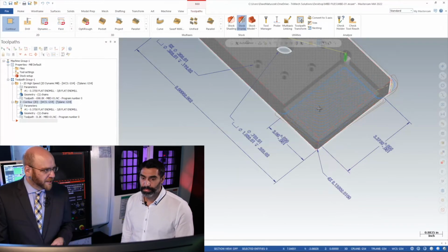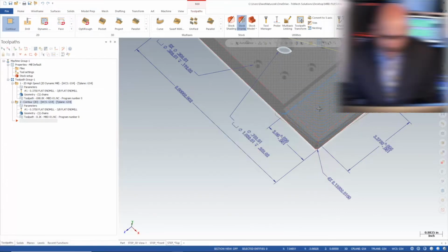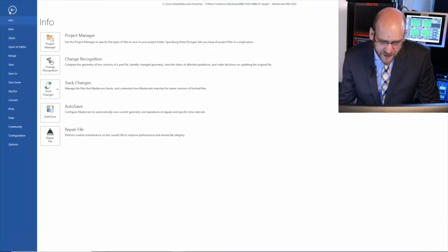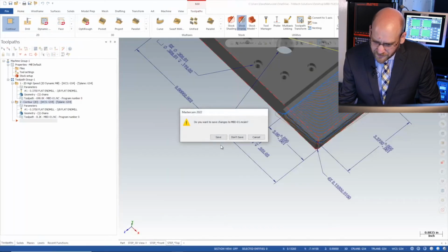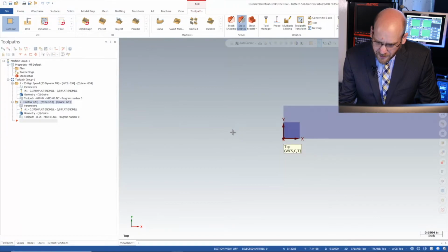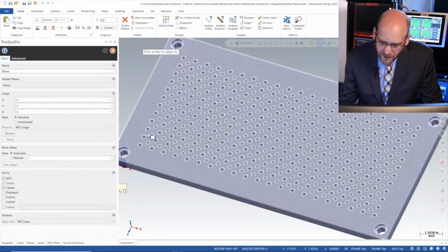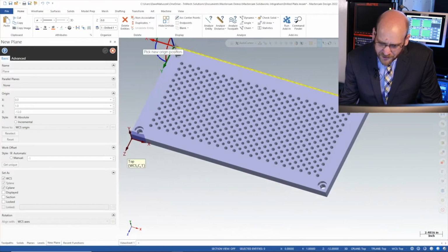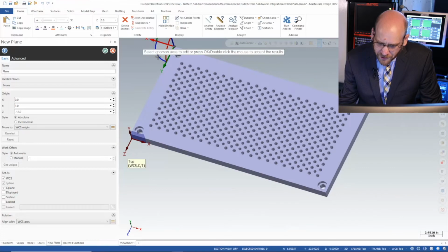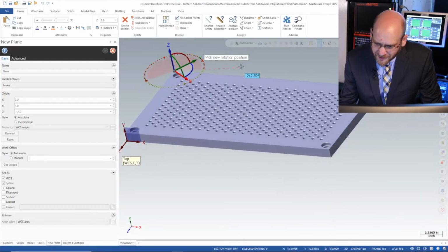And let me show you another neat thing that I can do using some model-based definitions. A real common thing that you might run into, I have a SolidWorks part here. This plate has a lot of holes in it. And one common problem you might run into, for those of you who don't know, the drill size for a 3/8-16 tap is 5/16 of an inch.